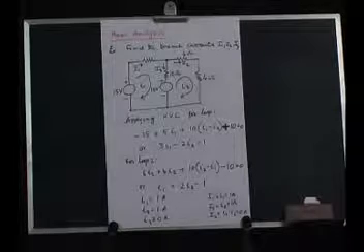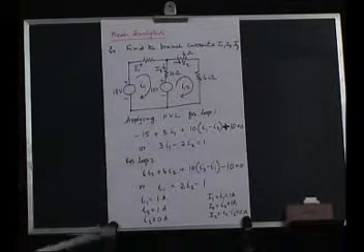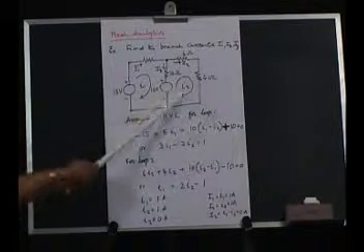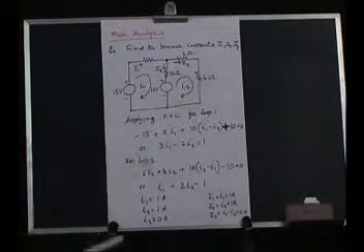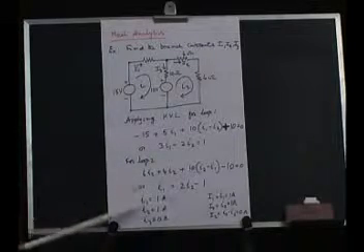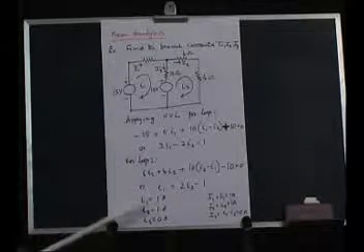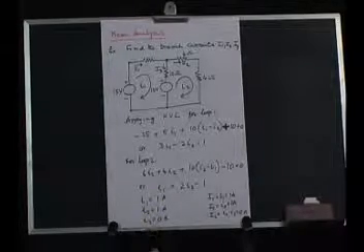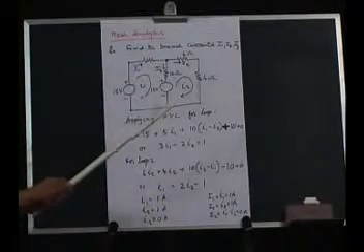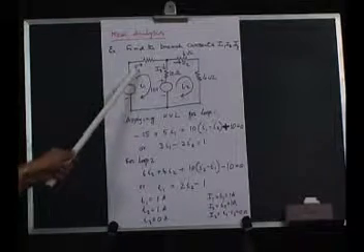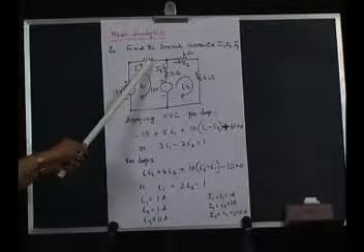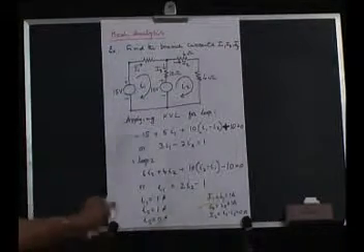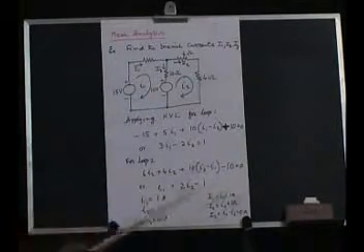So, therefore, we have 2 equations and 2 unknowns. One unknown is I1 and the second unknown is I2. So, we solve this simultaneously. We get I1 equal to 1 ampere, I2 equal to 1 ampere. How to find out the branch current? The loop current is the branch current as far as this resistance is concerned. That is why the branch current is the same as the loop current I1. So, we have 1 ampere.